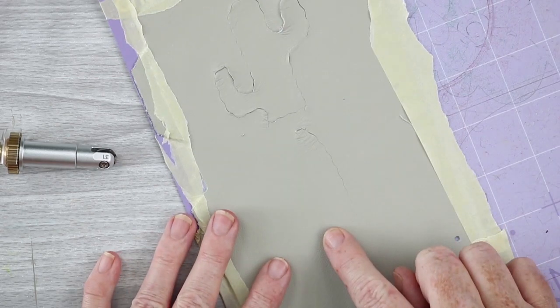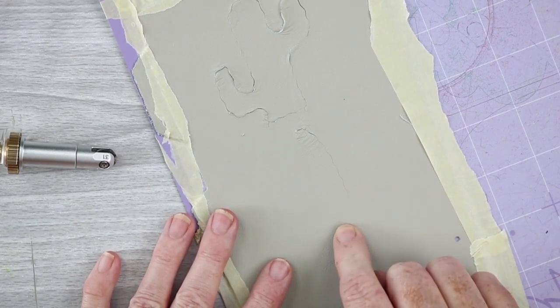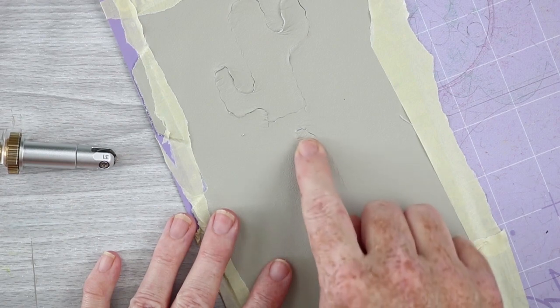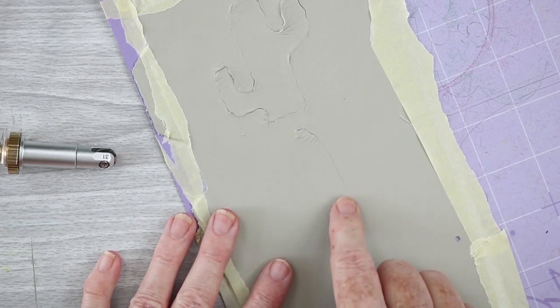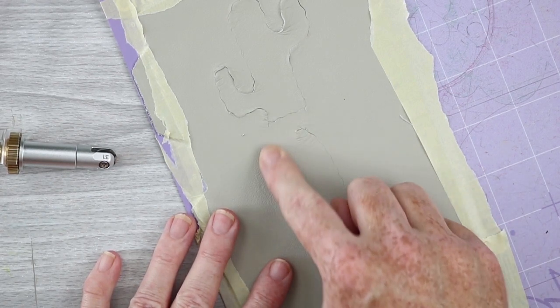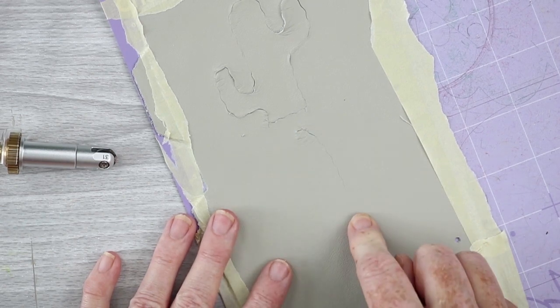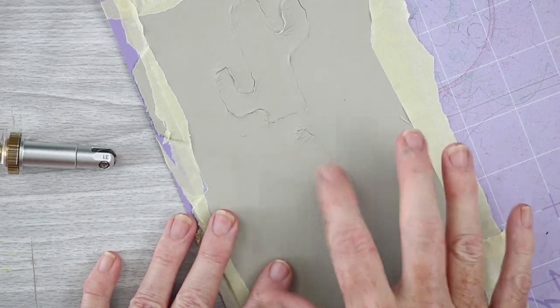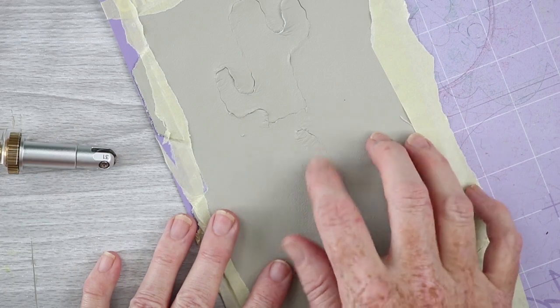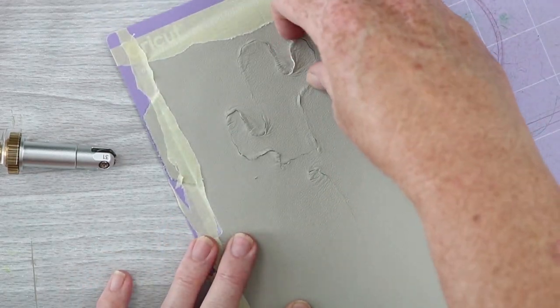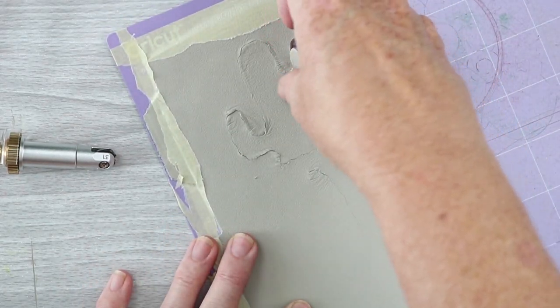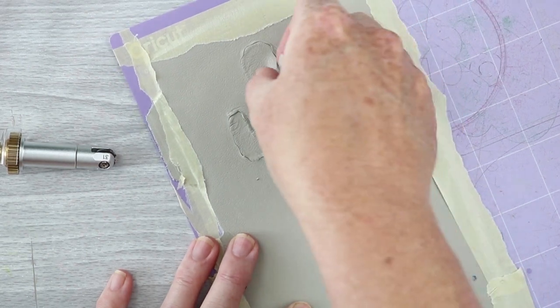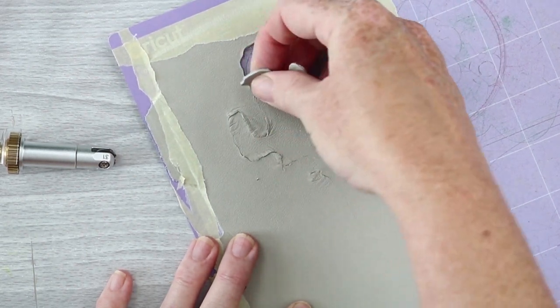The second one, as you can see, you might not be able to see anything because the blade got stuck. And this is actually the one that is just the semicircle shape. So it should have cut it perfectly, and it did not. So it did get stuck during the cut. So be aware that if you're cutting leather, you might need to make your curves even larger.